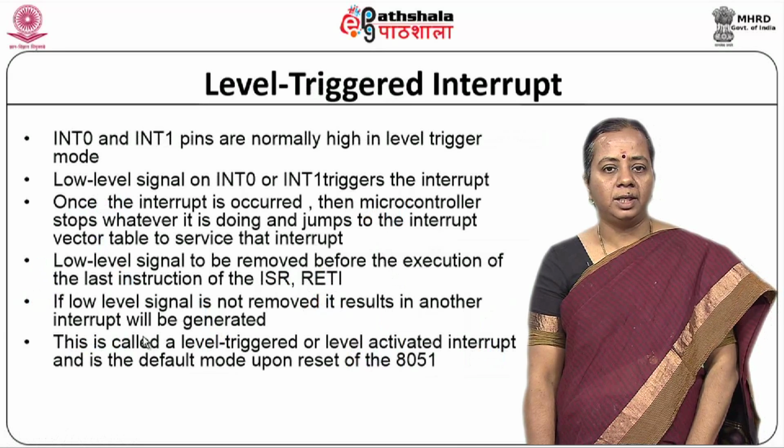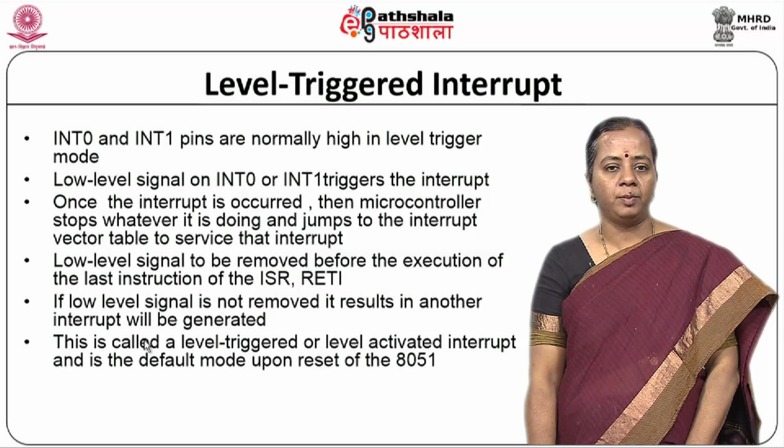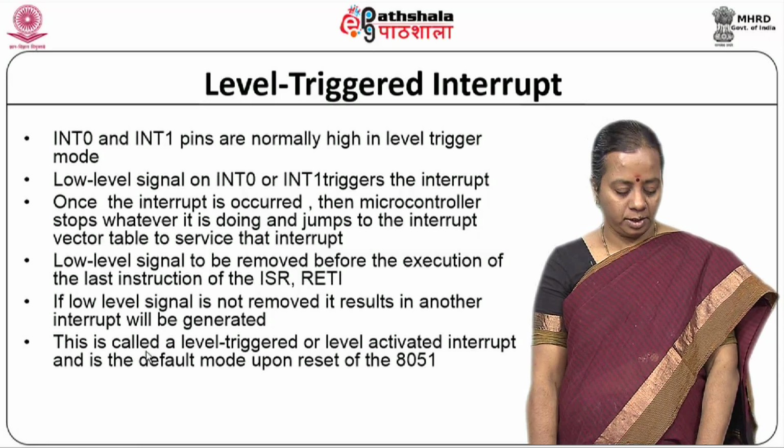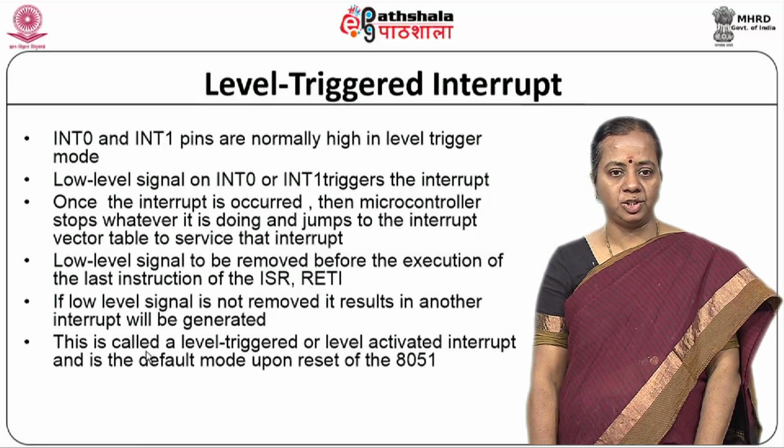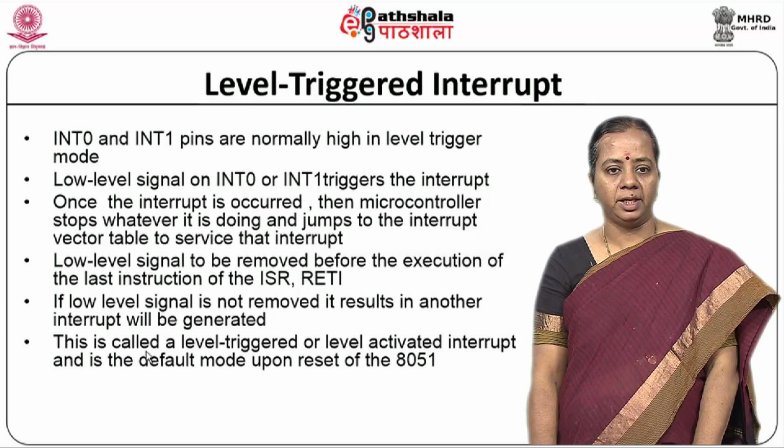So, in level triggered, if I am giving a 0, it invokes the interrupt service routine, and if I am using edge triggered, only at the transition does it get the interrupt service.